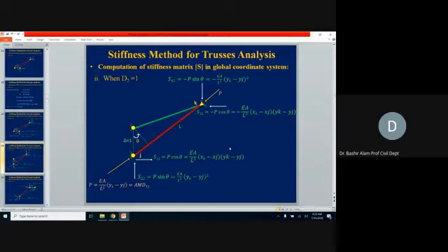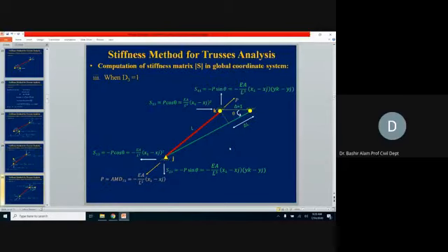The second column is now produced. Third, now corresponding to D3, here you see. We are sliding joint K to the right now. So this green is the new member now. Here if you see, we see an increase in length, which is because of the tensile force. So here you see P is shown away from the joint, meaning this member is going to come in tension.